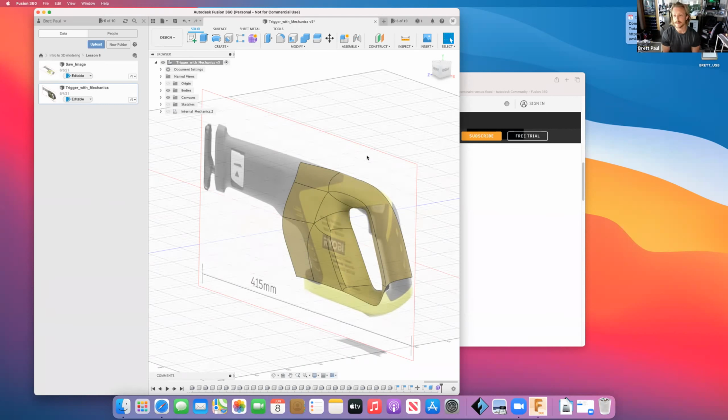I would say the biggest downside to freeform is that you don't have a history of all of your steps, and so going back and revising a really complex geometry can be time consuming. Also, when you go to spec this out or create a drawing, it's going to be really hard to capture, say, the angles and the overall geometry that you want using your standard drawing template, because it's not made from parametric modeling, sketches and extrusions.